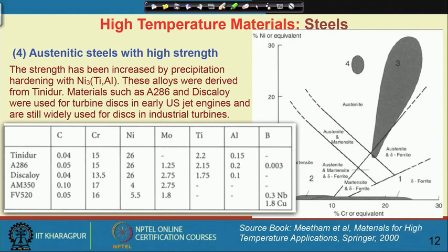And since I said that the region of those earlier steels was lying here, that was a class 3 type, and here this is the austenitic steel with a very high strength. So, this has a very low domain, and where are these materials to be used? Yes, when we need to use a material for brakes, then we need both higher temperature and high wear resistance. A high wear resistance comes because of the higher strength, meaning hardness or red hardness is required.